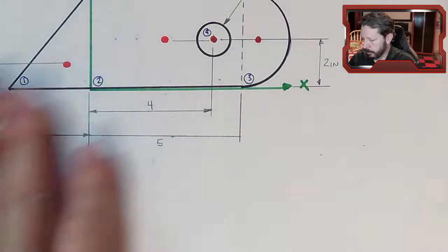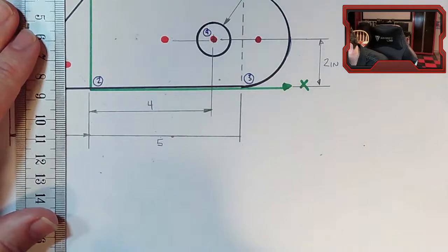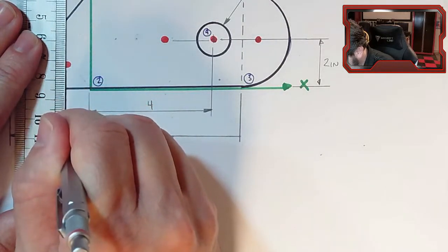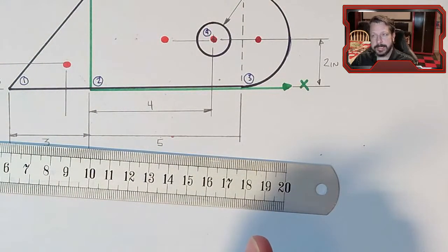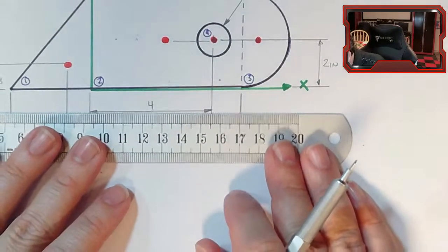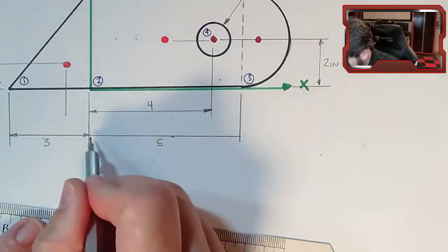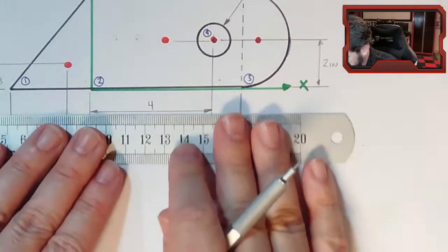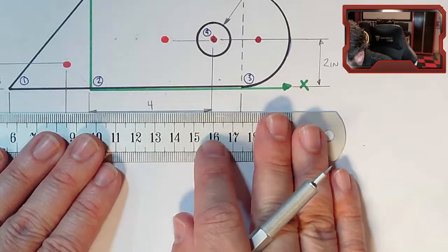So we have all of our y locations. Now we need all the x locations. So let's do the triangle again. Now you might remember we did the triangle by integration, and we came up with x sub c is 2/3 of the base. So this is why I draw things out. Also, when you have leader lines that line up, you normally do line them up. You don't offset them a little bit, because if you offset them, you make a significant gap between them. So we'll line this one up here.